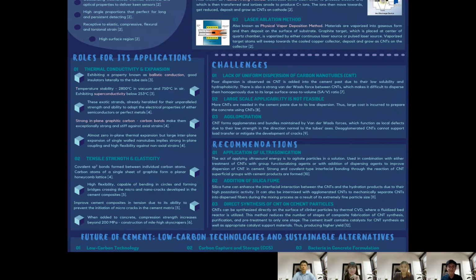Hello, my name is Shendaryn, and today I will be presenting on the challenges of using carbon nanotubes in cement for construction applications and some recommendations to these obstacles. Firstly, due to the low solubility and hydrophobicity of carbon nanotubes, a lack of uniform dispersion is observed as CNT is added into cement paste.